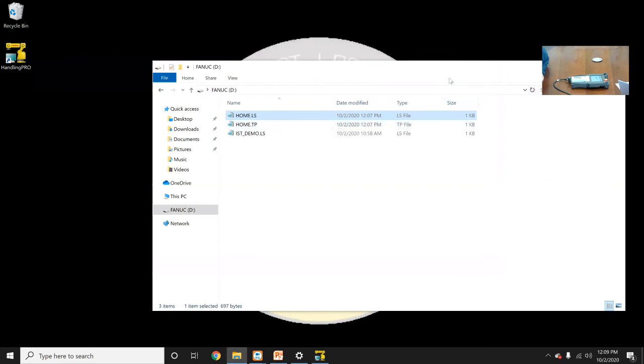So now I pulled this out of here. Now you can put it on your actual robot and go in and test it, run it, and make sure, as a validity point, that the students have created this program. Did they use the correct I/O? Did they use the correct joint or linear move, the correct termination, all of that? Take it, put it on a robot, and actually try to run it.